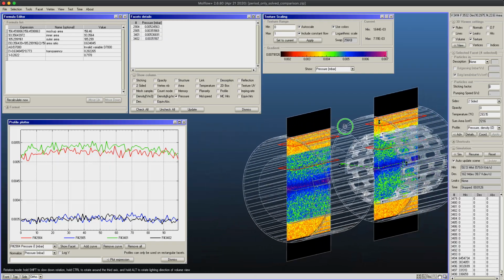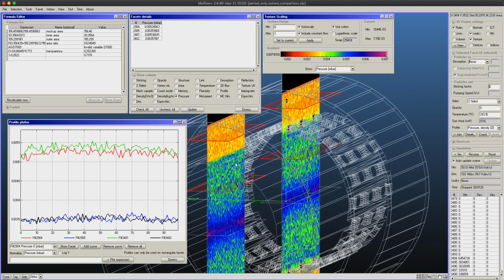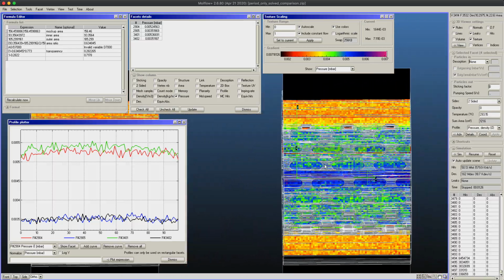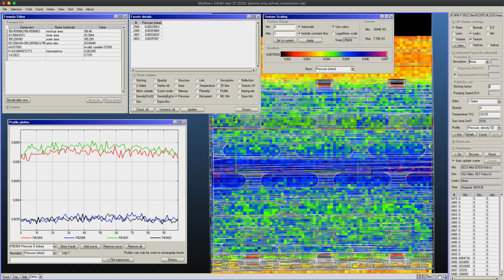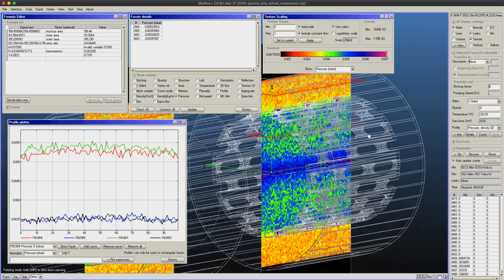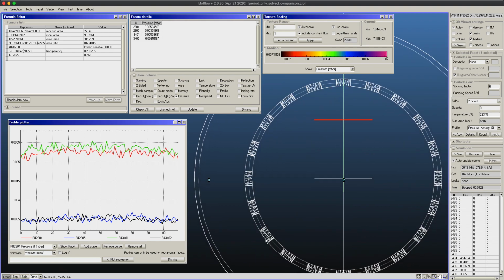So why is this? There are several reasons. So first of all, here we have used only 36 sides, so this is not a perfect circle. This geometry was slightly more detailed. Also, I was only using 3 periods, so probably the cutting is not perfect. If I used more periods, it would be a better approximation. And finally, I also realized that when I go to the front view, you can see that I was taking the average of the two diameters, and then in my calculation I was taking the average of the two areas. But actually the areas scale with the square of the diameter, so this averaging is also bringing a little bit of uncertainty.